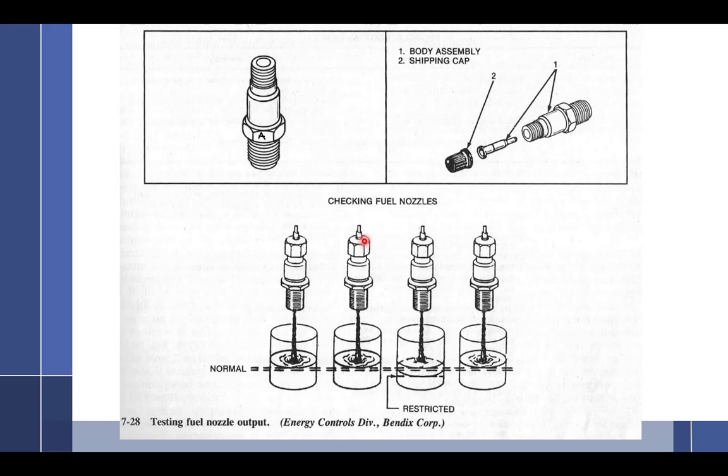What had happened is when you build hoses, when you do it, you'll see, but you have a rubber hose, and these metal parts go in and they're very sharp. And as they go in, they have a tendency to, like a razor blade, skim off some of the rubber. And I talked to a guy who made hoses for a living, and he said in their hose shop, they'd actually seen a time or two where somebody had got a little bit crooked and filed off enough of one part that it made a flap. And what does a flap do in a hose? Check valve. Made a nice little rubber check valve out of it. Anyways, this Cherokee 6, it almost went down. Guy barely made it to Franklin, was losing power and just had enough to get to Franklin.